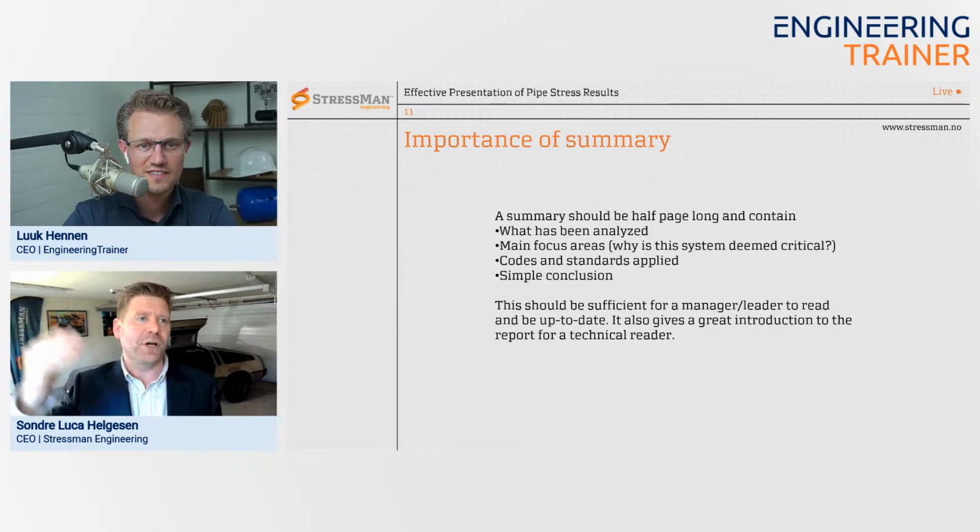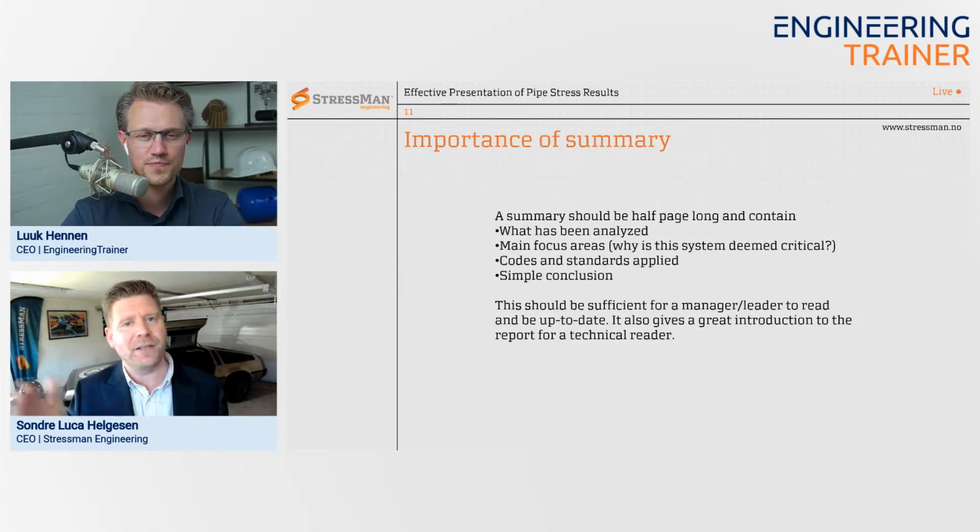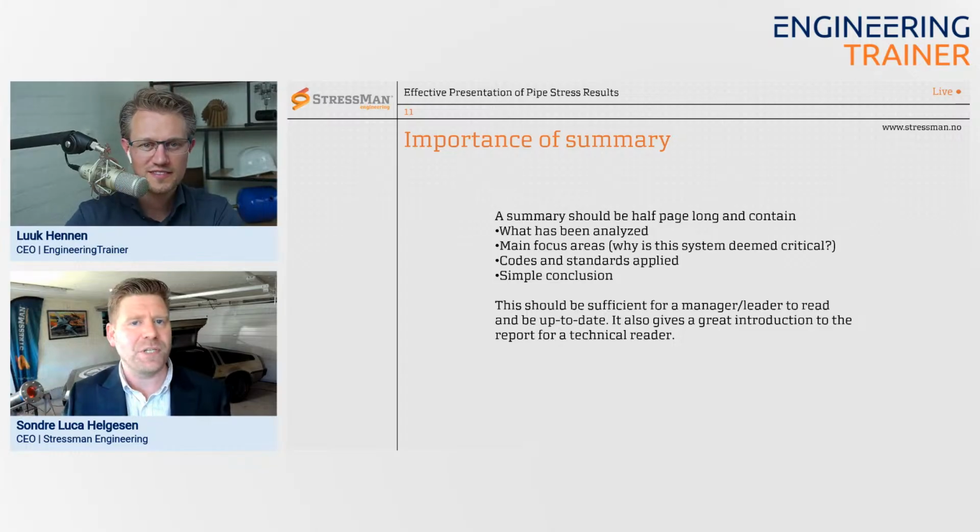So we had a master document, and we documented everything. Then suddenly one component was failing by 4 or 5%. But then we switched method to an elastic plastic analysis, for example, instead of purely elastic, and we were inside the acceptance criteria again. But then you only had to make that change in one report, not write about it in every report.